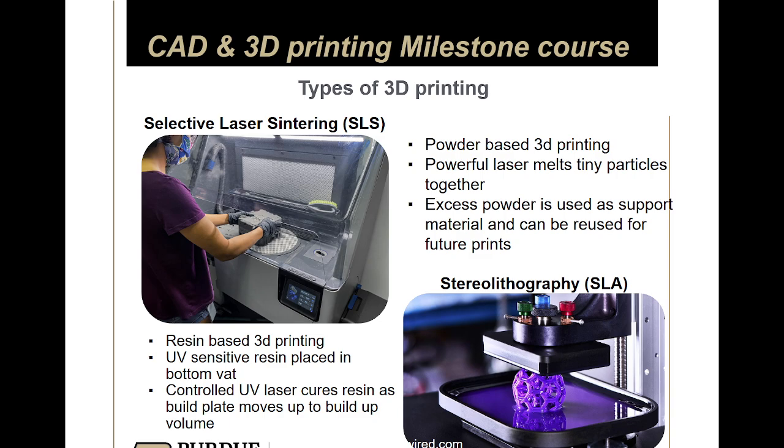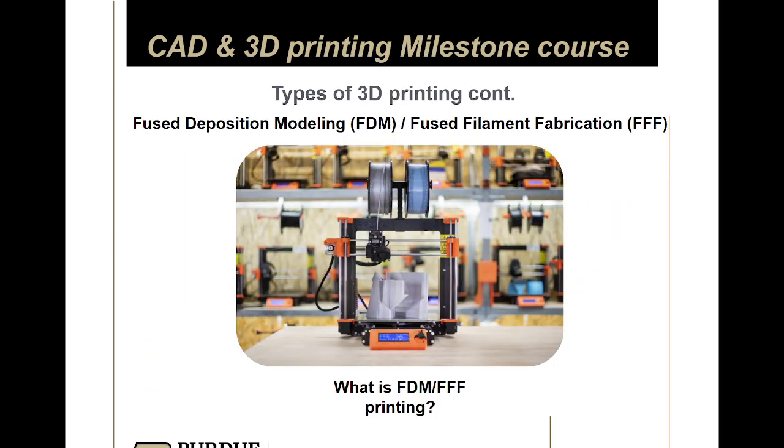But the one thing that I haven't talked about yet, which you're probably thinking about, is FDM 3D printing. So that's the main topic for today. We're going to talk about what it is and how you might design your parts to cater towards an FDM design. So there's technically two terms for FDM because FDM is technically a trademarked name. I think Stratasys has a trademark on FDM. So if you ever look it up, most companies will use FFF instead, but they basically mean the same thing. So I might use those terms interchangeably today, but they're just the same thing.